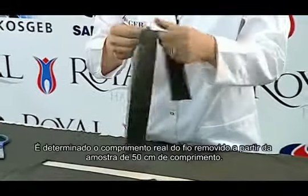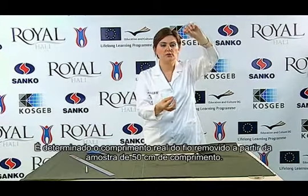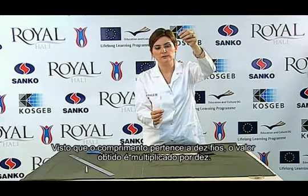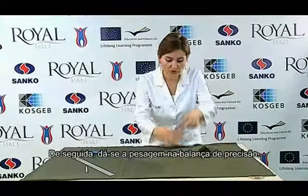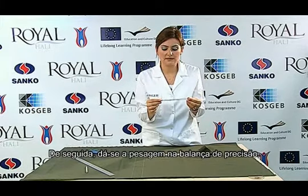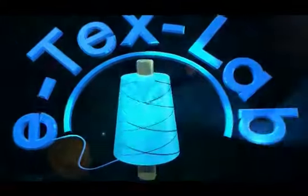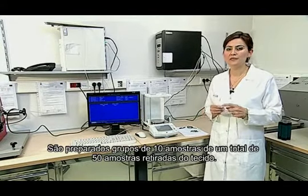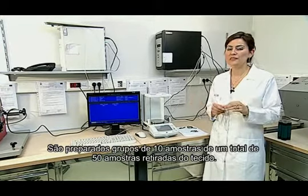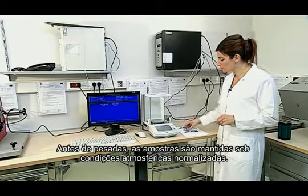We find the actual length of the yarn that is removed from the 50 centimeter long sample. Since the length belongs to 10 yarns, the obtained value is multiplied by 10. Then we weigh it in a precise balance. We prepare groups of 10 samples from a total of 50 samples that have been taken out of the fabric. Before weighing our samples, we condition them in standard atmospheric conditions.